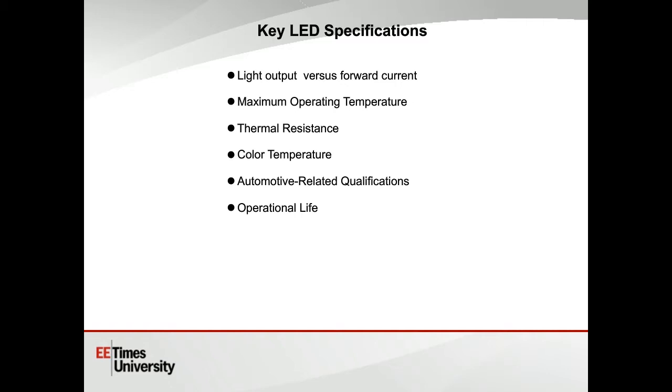We talked a little bit about some of the SAE specifications that talk about LED operation in automobiles. SAE J2650, for example, specifies the operational life in terms of the number of hours that the LEDs can maintain a minimum, typically 80% of their initial output. And because this is a statistical metric, the number is specified in percentages and confidence level.